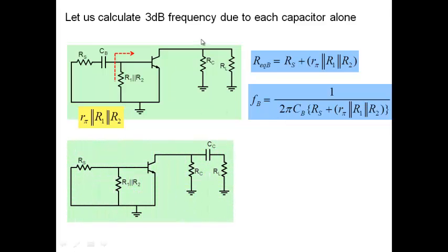All right. Let's focus on CC here. Once I look at that, CB becomes a short. This becomes a short. What will be the value now? What is the impedance seen from here? R naught. Between the collector and emitter, the resistance is R naught. So what happens? Resistance seen from here is R naught parallel RC. And we have been saying that R naught is much larger than RC, so we approximate it by RC here.